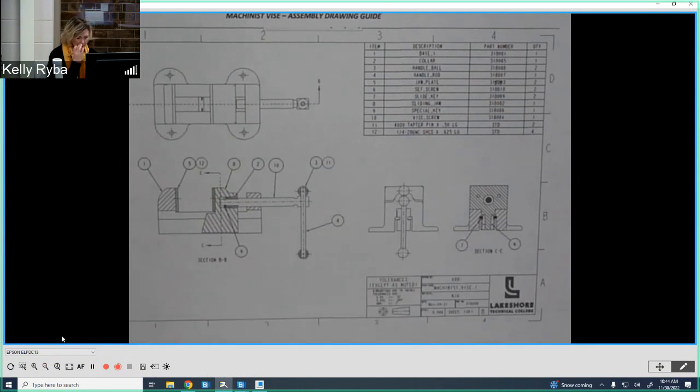Let's look at the GD&T on individual parts. So what I've done is I've targeted some parts. Now, we're not going to put GD&T on each and everything. You always want to consider it, all right? But I also want to make sure that you understand that, especially form tolerances, we're only going to add them when it's a refinement on what the assembly or the dimensions are already giving us.